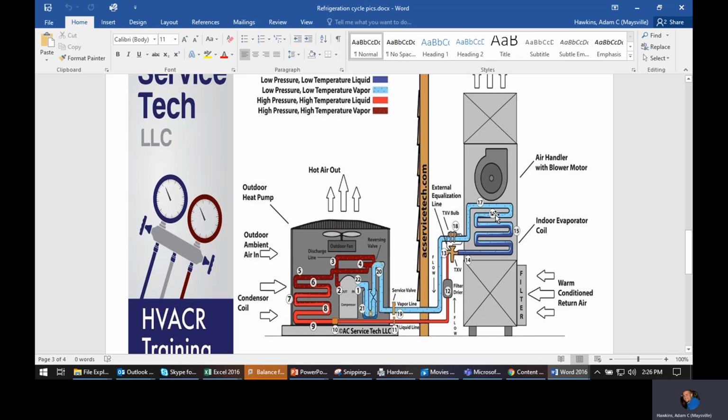And so that means that in addition to 100% vapor, we're going to put in a little bit of superheat, which serves a couple of different purposes. One of the purposes is it protects the compressor. The compressor, as we've already discussed, cannot or should not see liquid. If it does, that's going to create a problem, or it could create a problem over time. It's going to be bearing washout. It's going to wash out the oil. You could also just damage the parts just by dumping liquid into it. So you really want to limit that liquid exposure to the compressor. So superheat provides kind of a safety net or an insurance that the compressor is not seeing any liquid.